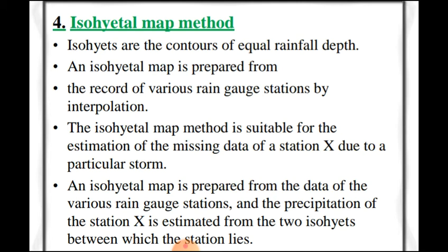And suppose P1 and P2 are the surrounding isohyetal values, P1 plus P2, and A is the area between them. The sum of the average precipitation times area for all the isohyets gives the areal average. Now once we get the areal average, we can know the depth over a certain area. Then we can prepare what are known as depth, area, duration curves.